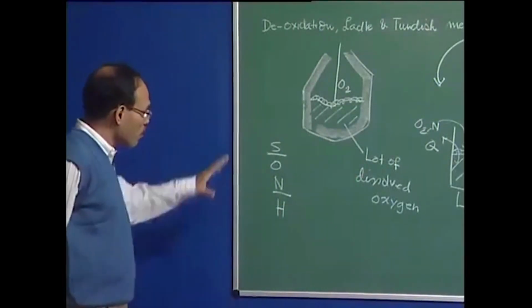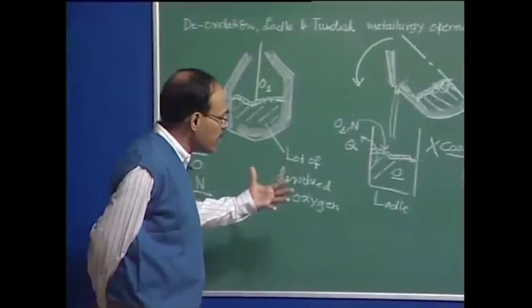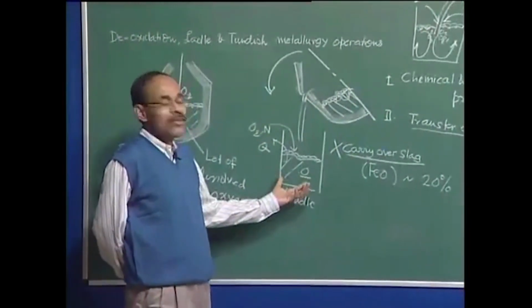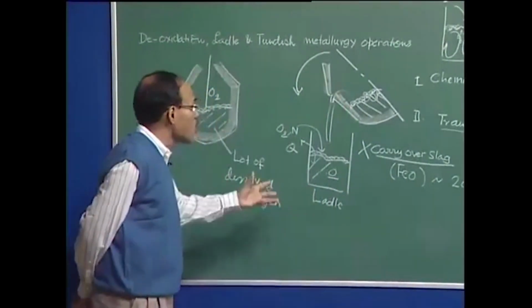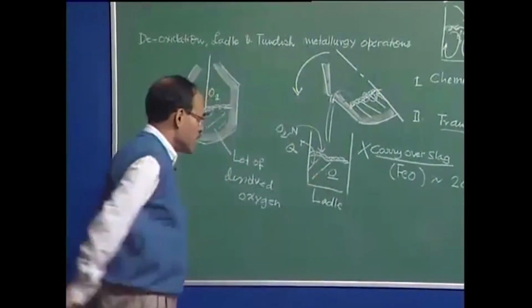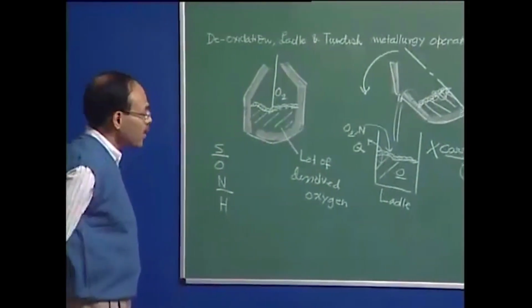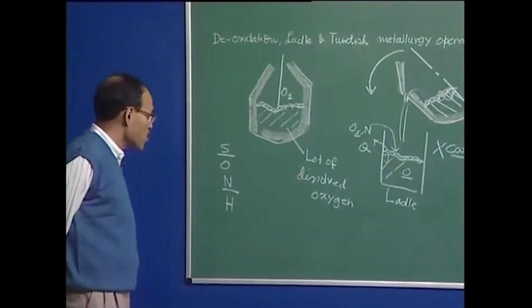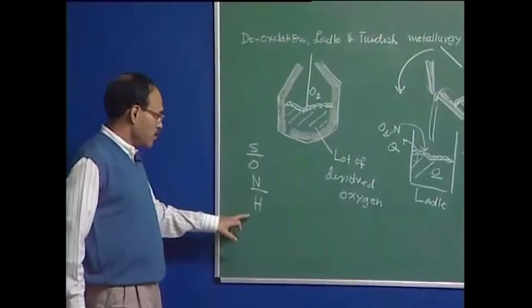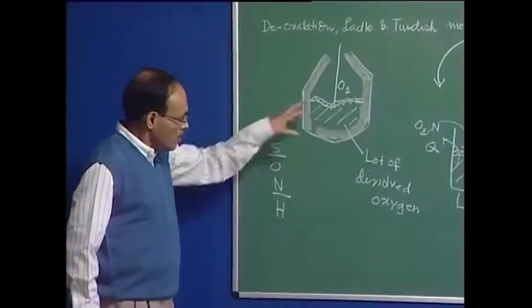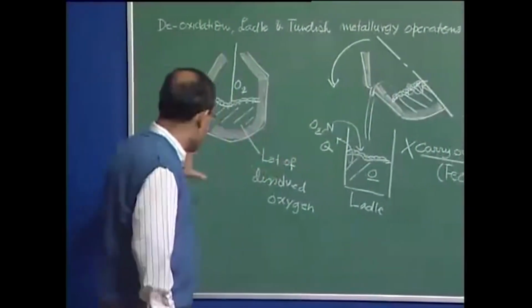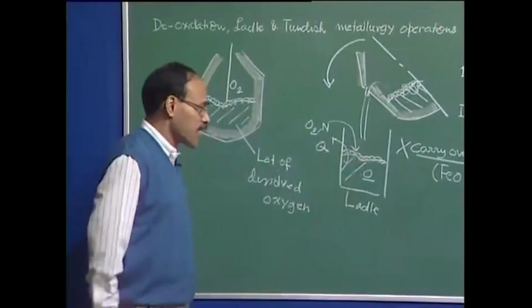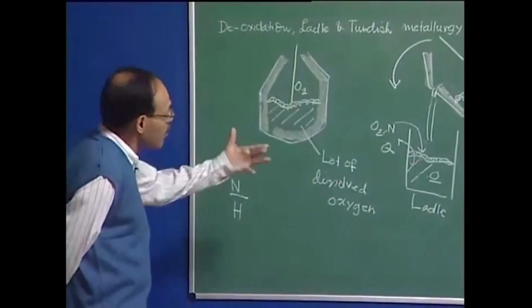must be adjusted, the composition, and also we may remember that we may not always want a plain carbon steel. There may be a demand for alloy steel, etc. So we have to make some alloying additions into the ladle also in order to get to the final desired composition. So these are unwanted elements which are present beyond the primary steel making vessel, primary steel making reactor or vessel, and these have to be eliminated in the secondary steel making process or in ladle metallurgy treatment.